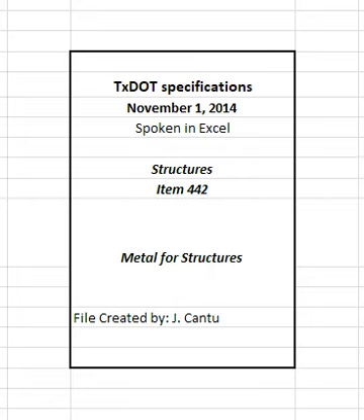Use the H frequency of testing for material with minimum specified yield point up to 50 ksi. Use the P frequency of testing for material with minimum specified yield point over 50 ksi. Ensure steel is sampled and tested in accordance with ASTM A673. 2.1.3 Other components.